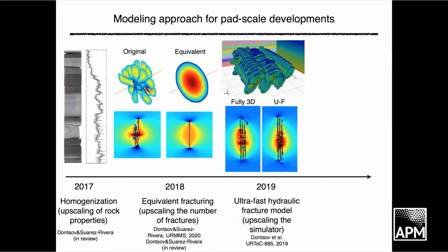And so we developed this ultra-fast hydraulic fracture model. Again, we've seen meta models for planar fractures before, right? But here it was elliptical, and we need to account for multiple fractures. We need to account for stress shadow between the fractures, okay? So here, in contrast to using data science, we actually use reduced physical modeling, kind of like pseudo-3-dimensional modeling, but reduced even further to an elliptical fracture. So it's still a physical model.